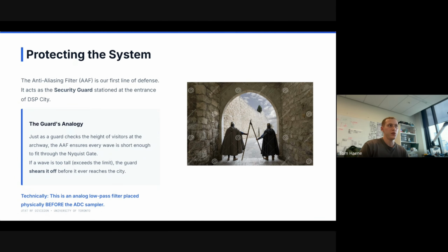No, if you design your filter correctly, essentially the way you design your anti-aliasing filter is you know what frequencies you're interested in. If I only care about up to 20 kilohertz, I'm going to design my anti-aliasing filter to have a cutoff at 20. So I see your point, but it's not technically true. You could do it in digital.